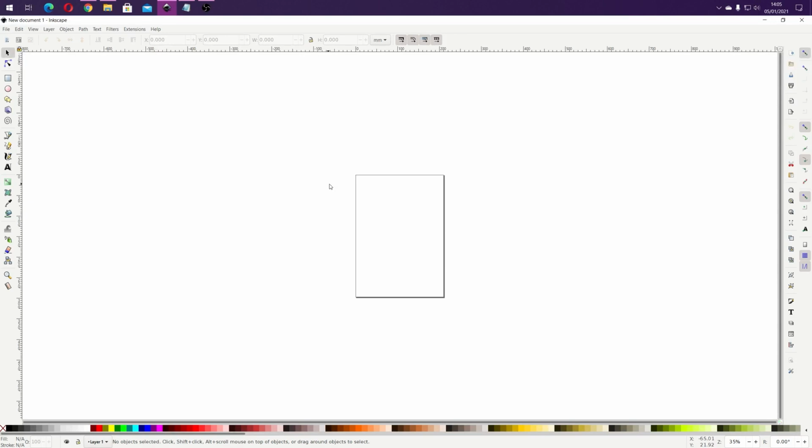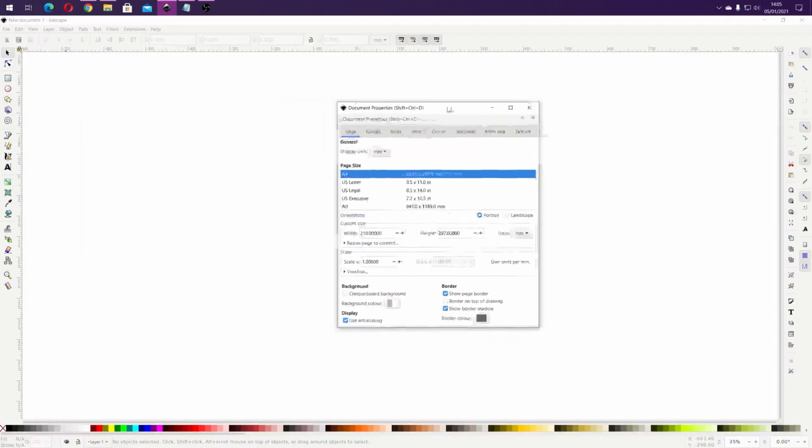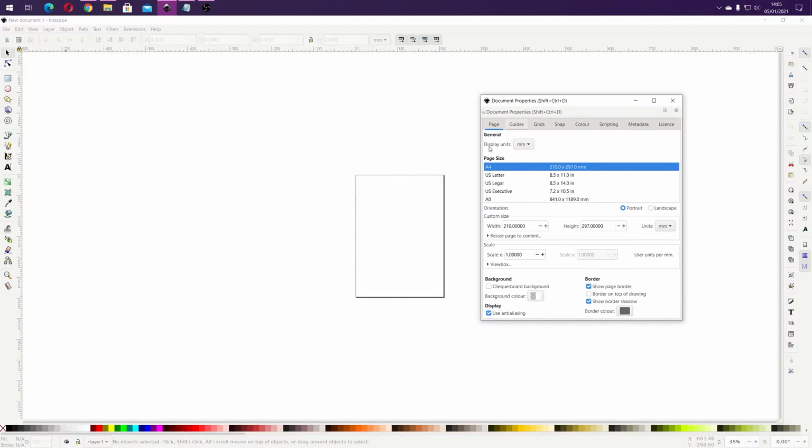So let's jump to basic properties, which are document setup. So the first tab, File, and the document properties. Actually the first tab are essential, and important are 4 tabs. So the first, about page, the general display units. You can choose from the list millimeters or pixels. I prefer that too. You can change that, and all units will be automatically recalculated.